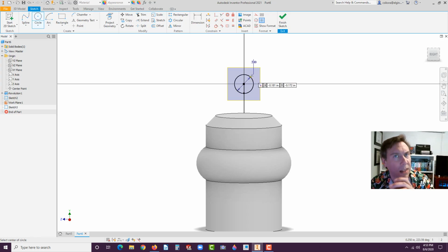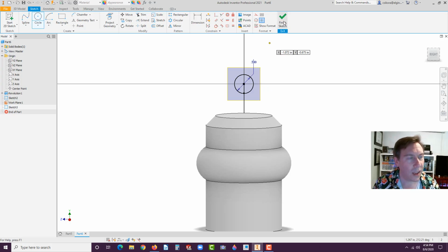Now, because I'm letting you have carte blanche on how that curve's looking, if you have a very tight curve, it may fail to sweep a 1/2 inch diameter circle. So if you have that issue, because I'm not there to actually see what you're doing, my recommendation might be to either smooth out the original curve or just make this circle smaller so that you could get past it, and maybe make it 0.25 or 0.125 if that fails. And usually one of those will work. Just from my experience teaching this as long as I have, I've seen a lot of students have a little bit of a challenge there because we didn't use a dimension.